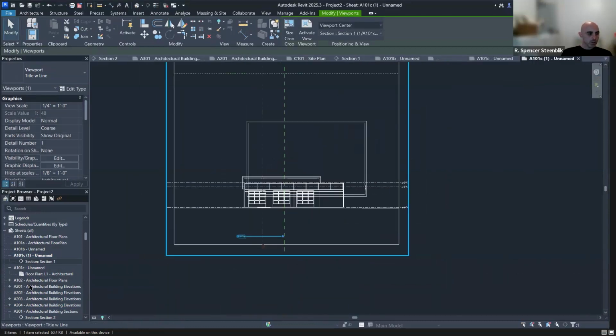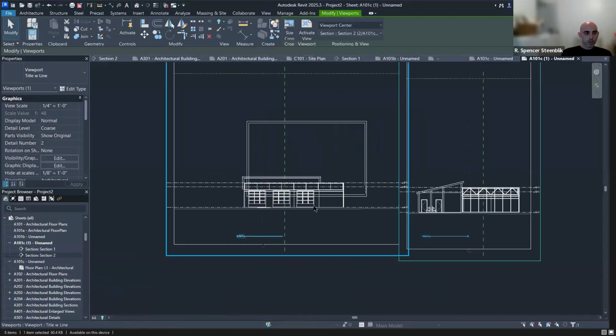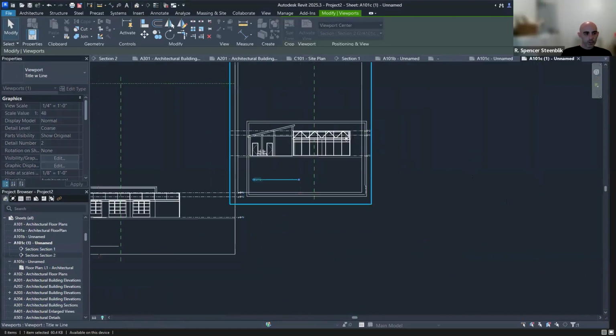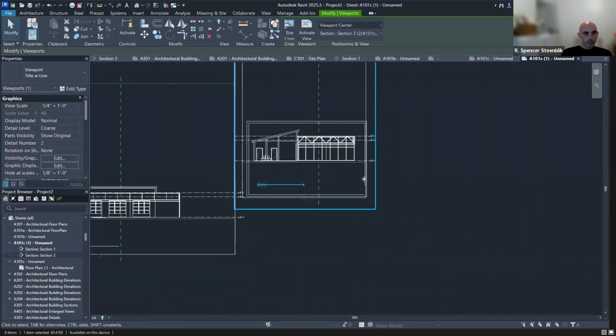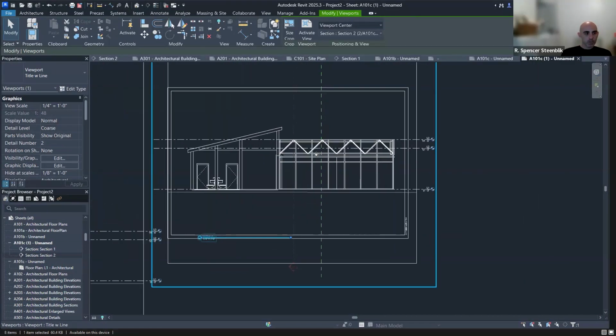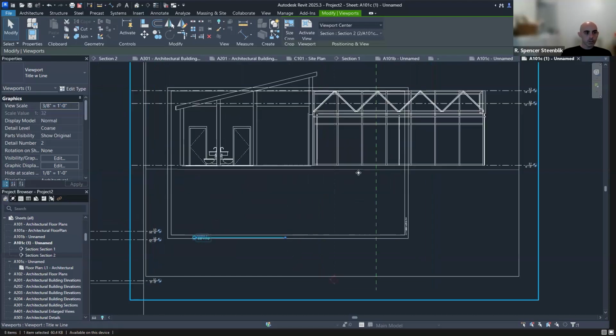There's our section 01. Section 2 is smaller, so that one would work better to work directly on that sheet. And I think if you scale things to be a little tighter, you can get that to fit. It's a 1/4 inch on the sheet, you might go down to 3/8. Oops, sorry, down to 3/16.